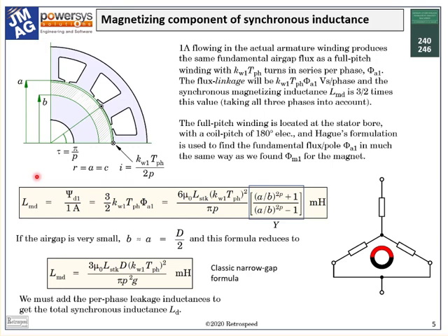Recognizing that AC machines produce torque from the fundamental space harmonic components of flux and ampere conductors, it has always been of interest to know the inductance associated with the fundamental ampere conductors, in particular when all three phases are working together in a balanced condition. That's what we call the magnetizing inductance, a very old term, and it's not obvious from the name that it includes only the working space harmonic.